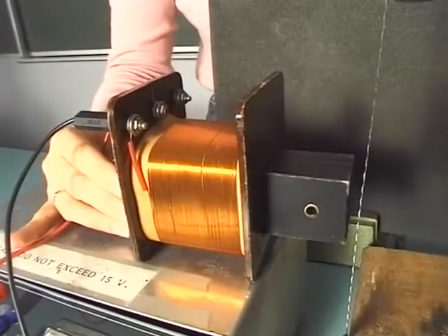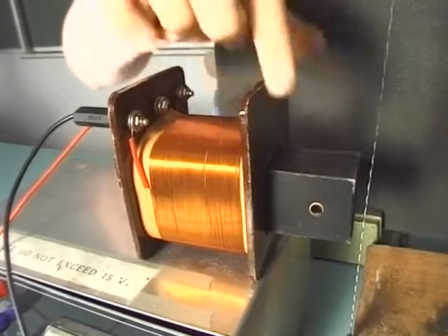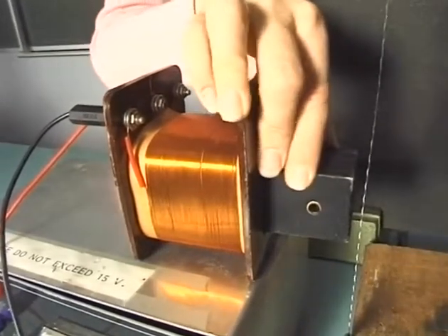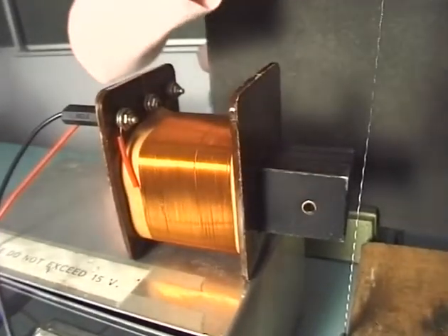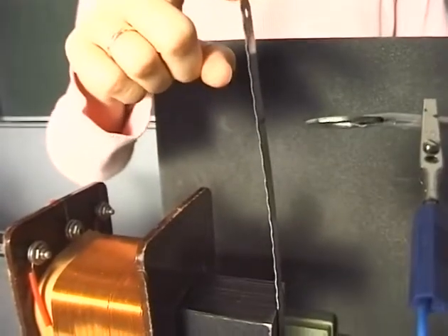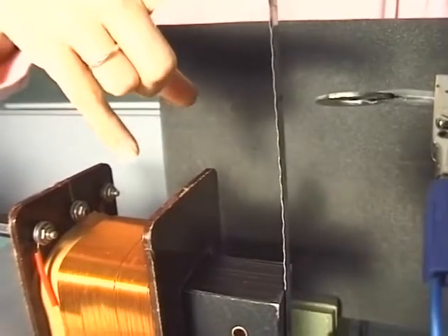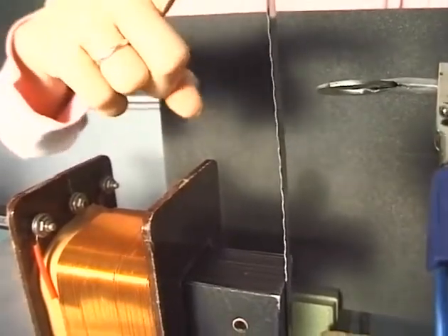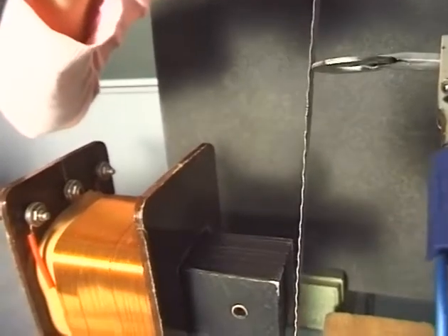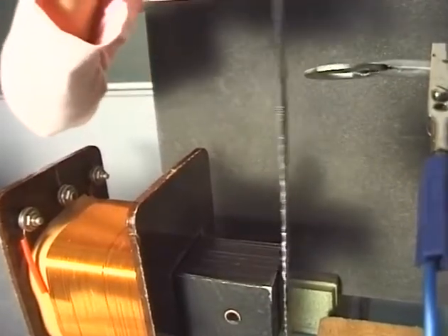When it is closed, then current will flow, and it will flow through this coil, which because of the iron core will act like a strong electromagnet. That magnet will attract the saw blade, and that will open the circuit, and so current won't flow, which also means in turn that this electromagnet won't be an electromagnet anymore, and the switch will close. So when we have the power on, it should oscillate between these two places.